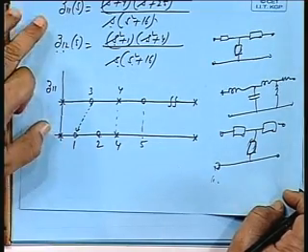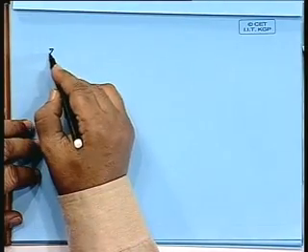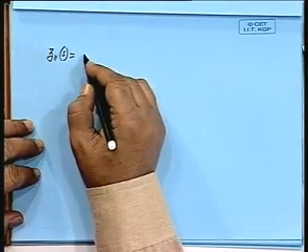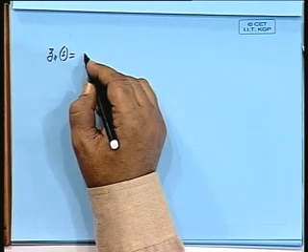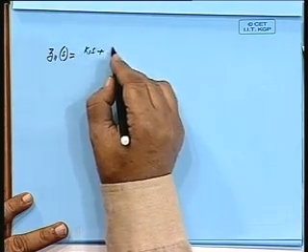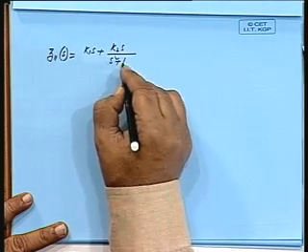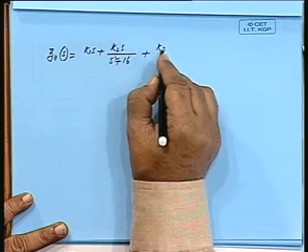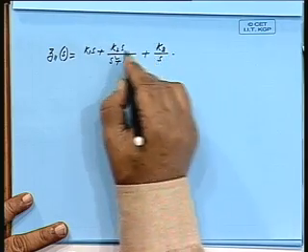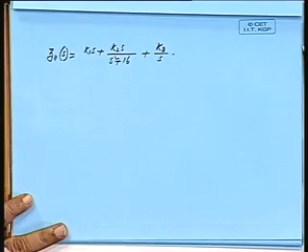Okay. So, Z11(s), let us break it up. Z11(s) you write as K1 s plus K2 s by (s squared plus 16) plus K3 by s. I am not really concerned about all these, I am interested only in a partial removal of this.